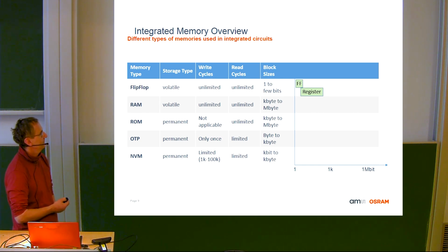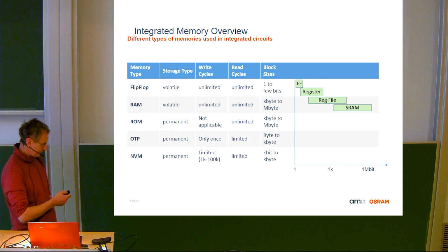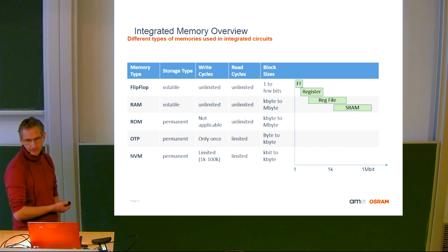But whatever exceeds this, you should consider using RAMs or register files. And registers are in the range of a few bits up to a kilobit. Then you start from registers, which are more or less also based on clusters of flip-flops, maybe a little bit optimized. You start with the register file, which is the easiest way to implement a RAM bit cell, for example.